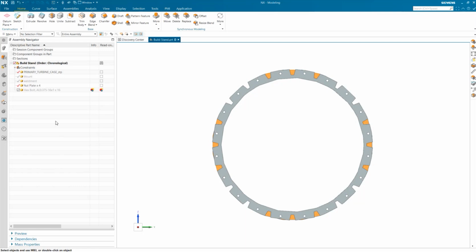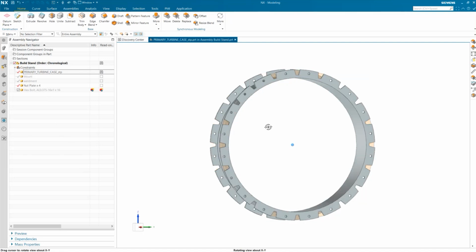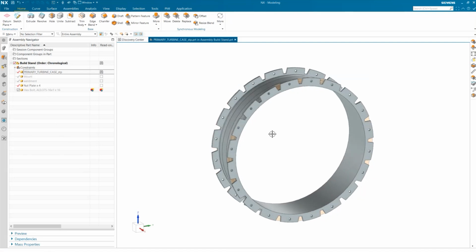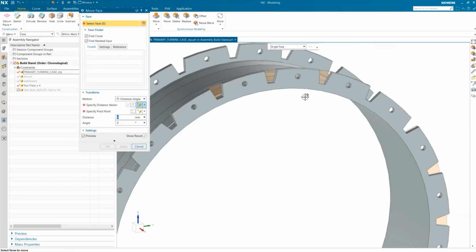Now, I'm an individual going in here to make my engine hardware change. I'm going real quick. I have somebody behind me yapping at me that we've got to get this done so we can get it out there today. So I'm not paying attention, let's say. Okay, they want me to go in and make a change to the engine hardware, and we're going to dummy proof this, or maybe we're going to put a hole and offset it so that we can use it as a datum. So we come in here and I'm going to go make my change. I'm going to go pick this hole right here.